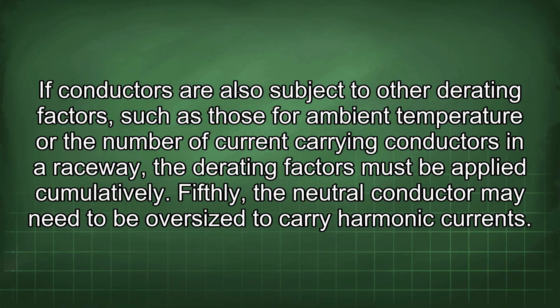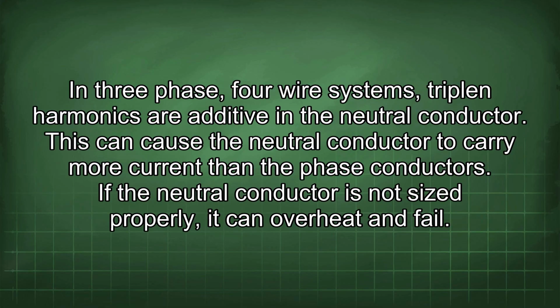Fifthly, the neutral conductor may need to be oversized to carry harmonic currents. In three-phase, four-wire systems, triplen harmonics are additive in the neutral conductor. This can cause the neutral conductor to carry more current than the phase conductors. If the neutral conductor is not sized properly, it can overheat and fail.